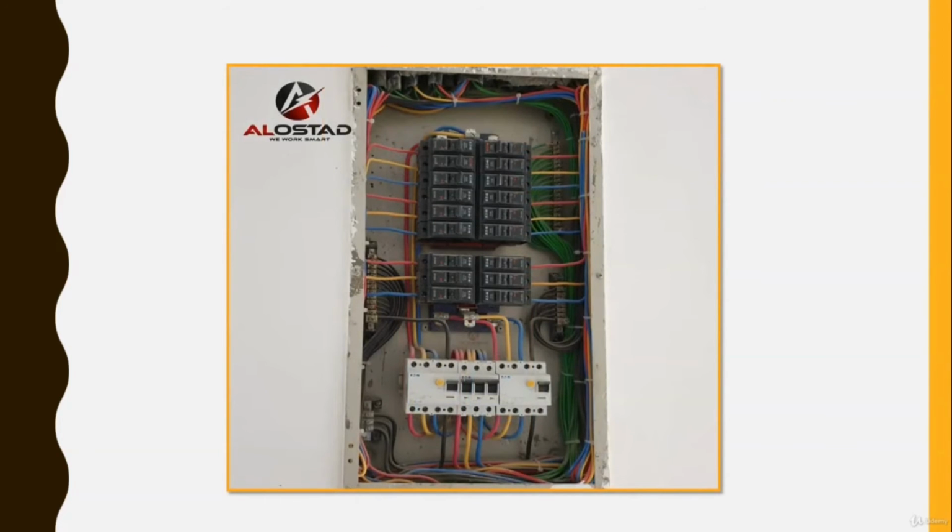Well, we have this DB now. Anyway, this DB is designed by a different person, not me. But yes, we can analyze it. Why not? So let's do it together. We have the incomer breaker, which feeds two ELCBs. Then the two ELCBs feed the bus bars. Of course, each one feeds one bus bar. Finally, the bus bars feed the MCBs. You can see the neutral plates. There are two, one for each bus bar. While here is the earth plate or earth joint. Simply, it's used for earth wires.